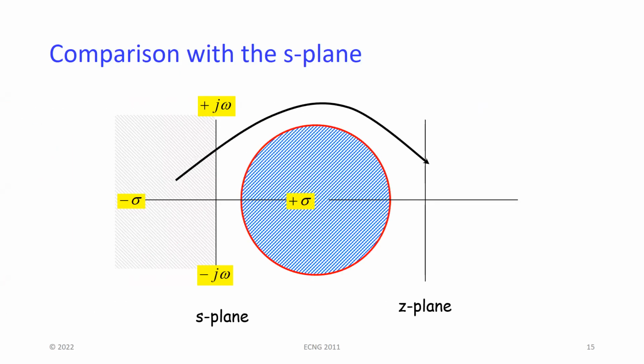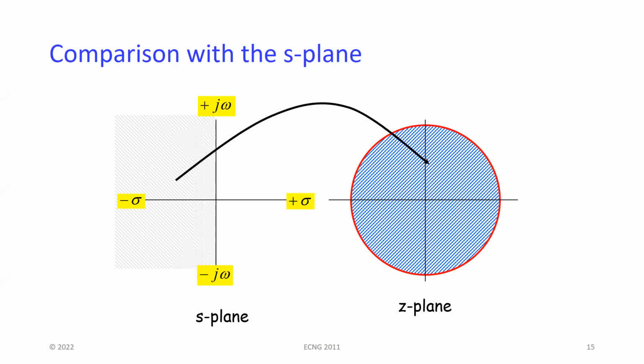The last thing I spoke about is that the left-hand side of the S-plane mapped inside of the unit circle. This is the stability business about all the poles of a continuous time transfer function being in the left-hand side of the S-plane. We explained that already: e to the minus st for the Laplace transform is really e to the minus sigma plus j omega t, which is e to the minus sigma t by e to the minus j omega t.